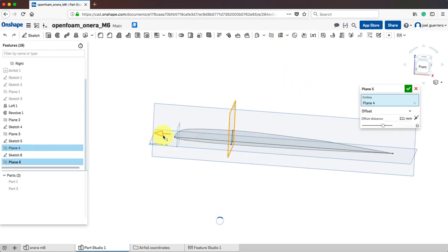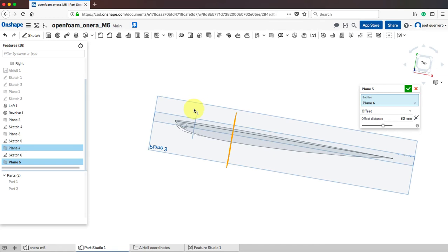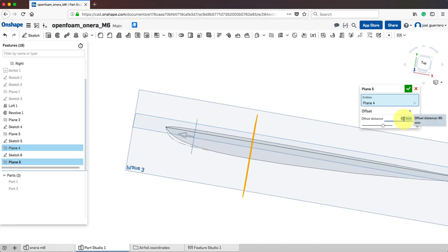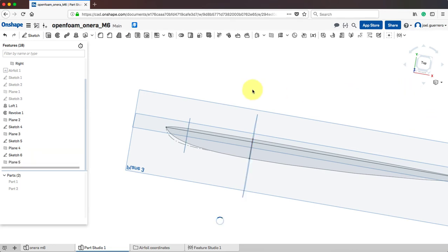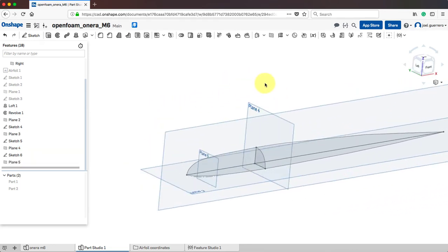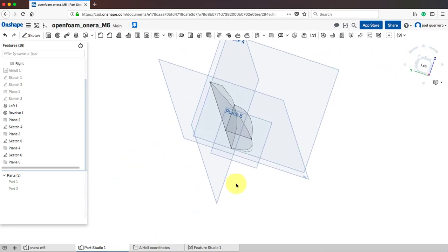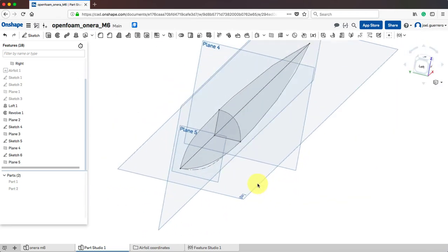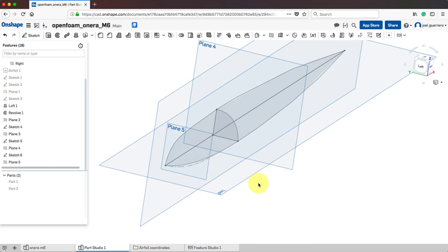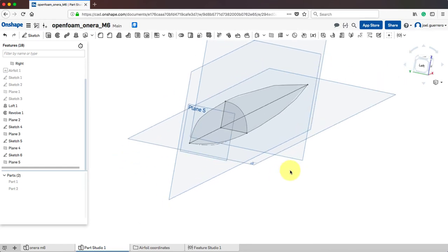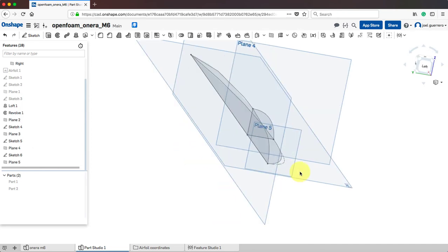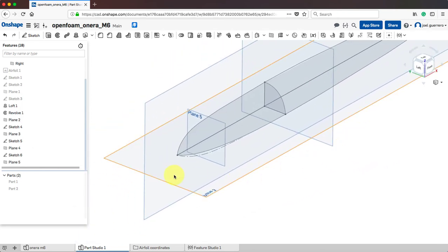Let's say that probably I want that plane at 90 millimeters. In that section I will create a new profile section to have more control. You can put as many as you want, but if you put 100, it's a lot of work. You need to create all those shapes. So I think 2 sections will give me enough control here.